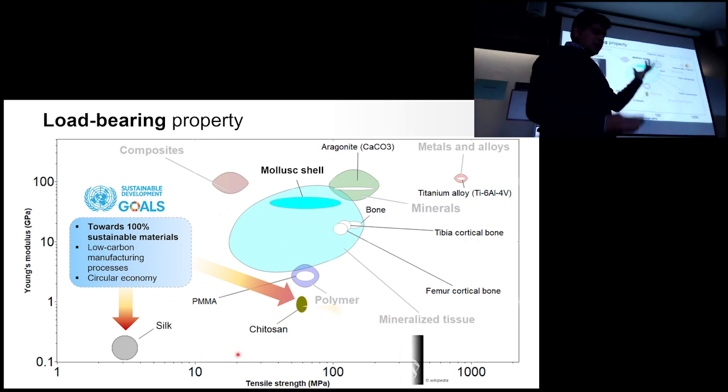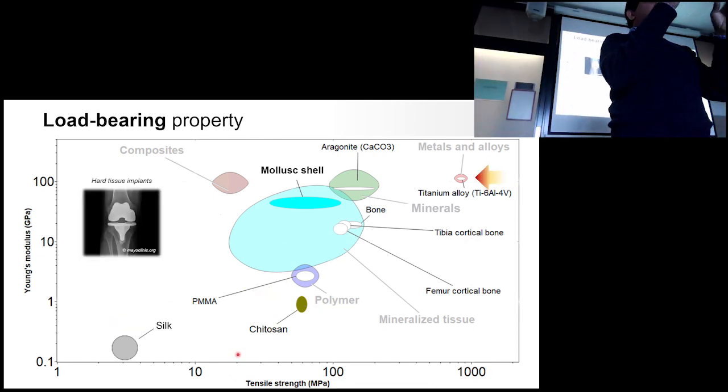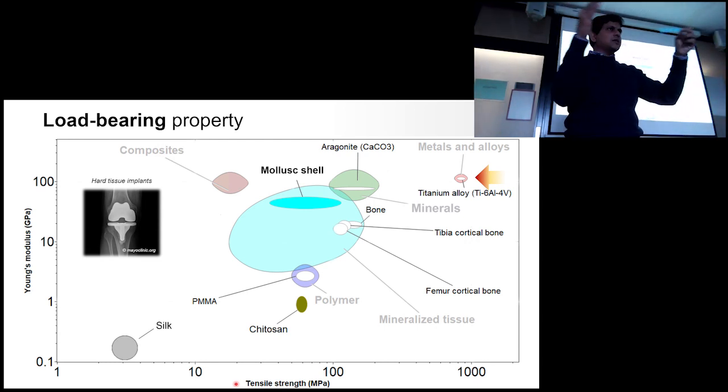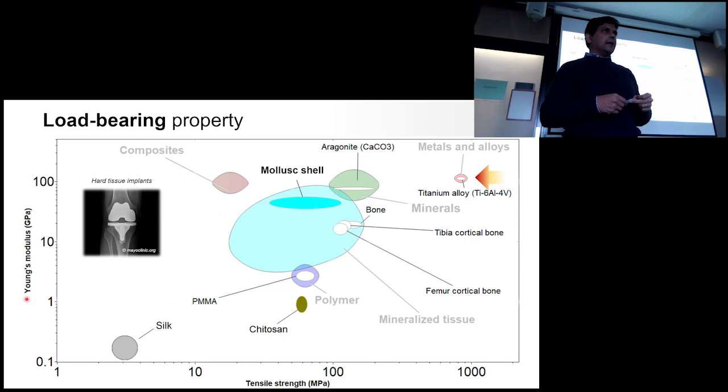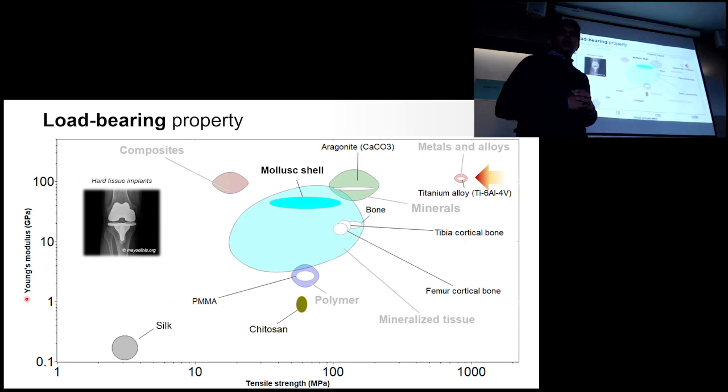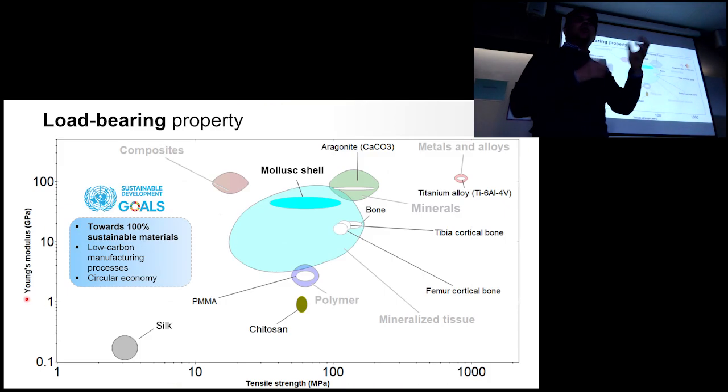And what these parameters, stiffness and tensile strength, basically mean, I can show you with this experiment. We take this plastic sheet and we initially try to pull at it, and it will initially stretch a bit, but when I release the load, it will go back to its original length. It will recover its original shape, right?